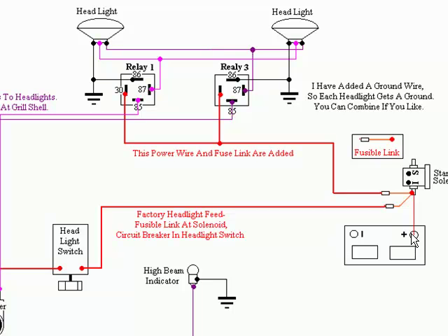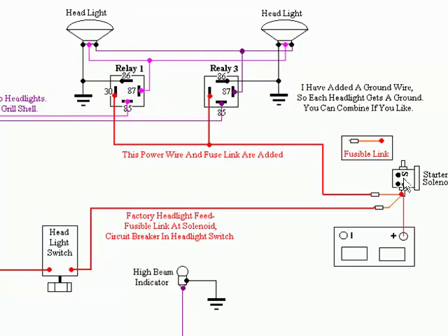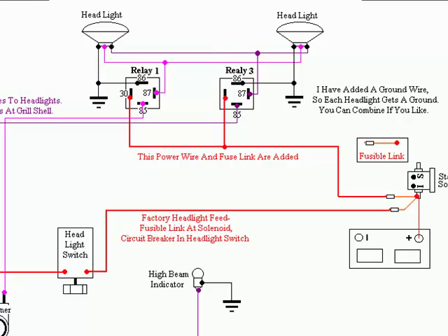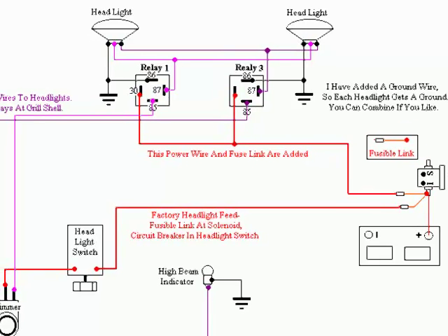Anyway, there's a wire going here through what is called a starter solenoid. That means this one here has to get started first for any of the headlights to be turned on. So in this kind of schematic, if your car is not running, the headlights are not going to turn on. So you're actually safe against what the problem says. But in some older cars, and some are still manufactured, you could actually accidentally leave the headlights on.